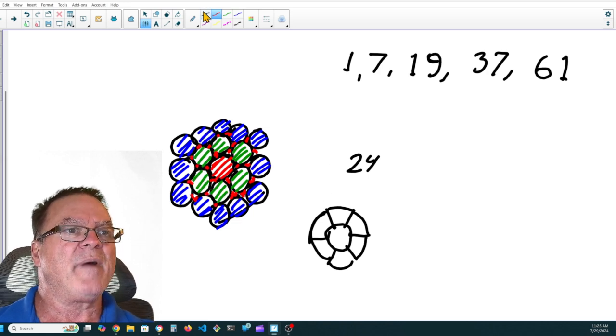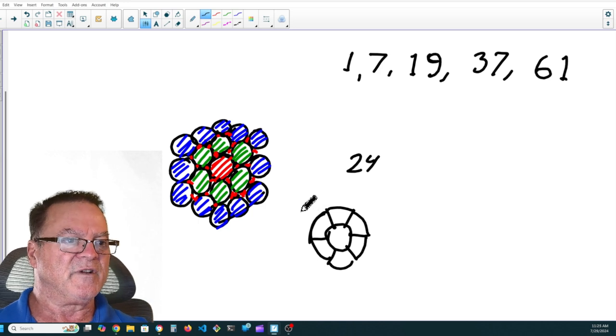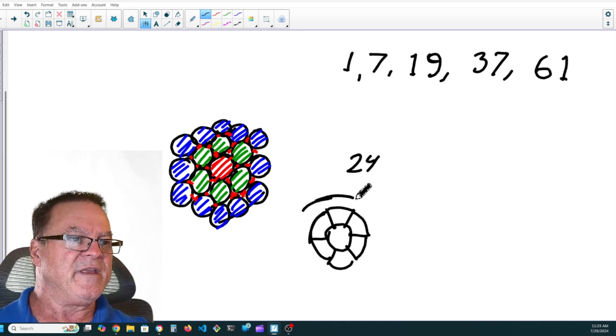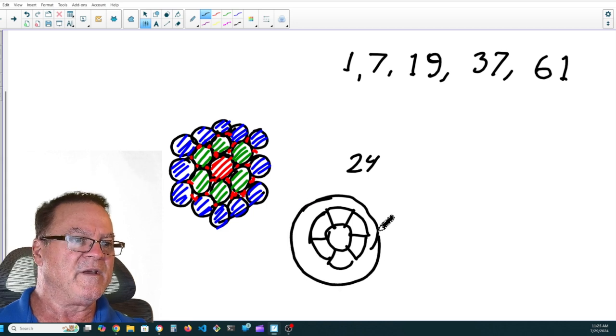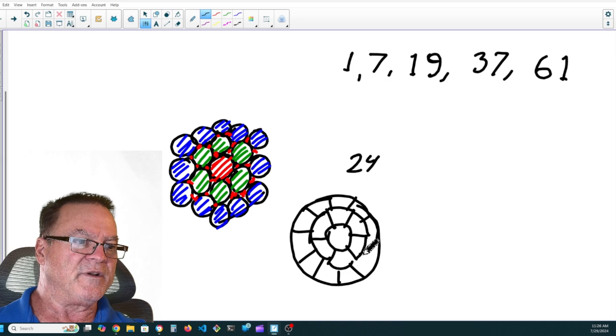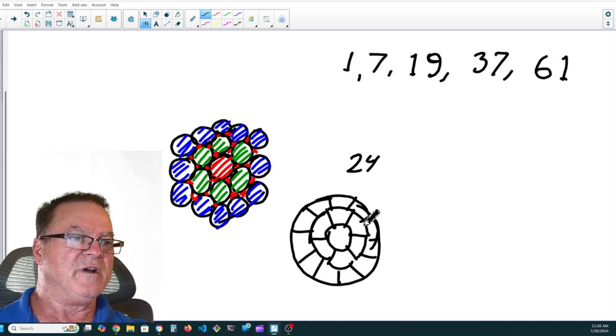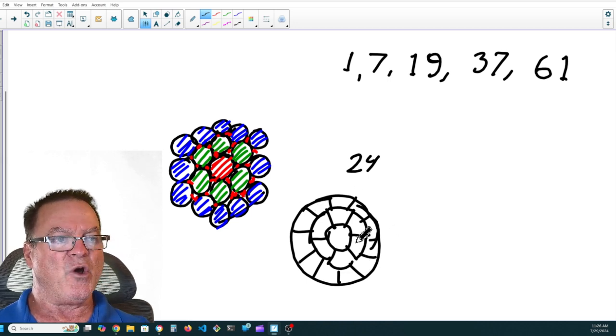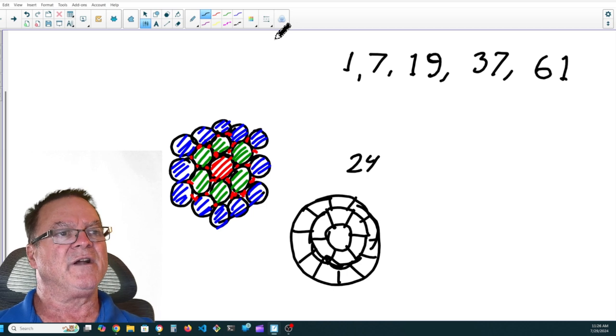What they do with compact conductors is they shape those individual conductors in such a way that they will stack up around the existing cable, and they fit very tightly with no air in between them. It makes it a little bit easier to pull into conduit.